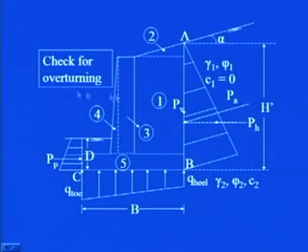So, as soon as the wall starts moving, let us say in this direction, due to the presence of this backfill, this side of the wall will be moving away from the soil. So, here active conditions will be generated. However, on the other side, if the movement of the wall is in this direction, the wall will be pushing towards the soil, and so passive conditions will be generated, and therefore the passive pressure will be generated over this much depth.